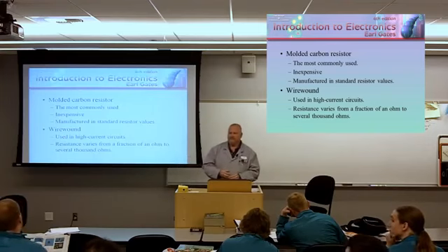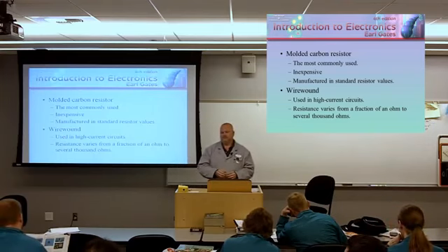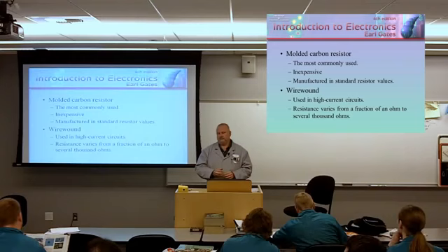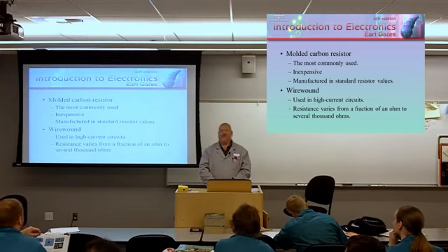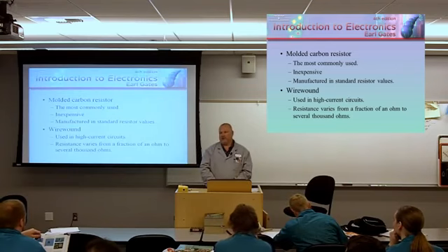Question? When you were talking about the tolerance, and you were saying if you bought a 100 ohm resistor and you found it's 103 point something, will that tolerance change, or will that resistor constantly be 103? It could change over time. Typically, it's going to stay pretty close to what it was. But again, since these heat up, things could change in the composition of it and alter its characteristics. But that's not a big factor to worry about.